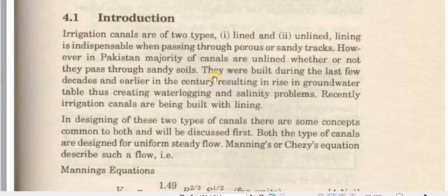And we will use the equations of open channel here. The sequence is that from the barrage we offtake the main canal, and the main canal diverts water to the branch canal, which diverts to the major distributary, and the major distributary diverts to multiple minor distributaries, and minor distributaries divert water to the water course from the outlet. We studied outlets in our previous lectures, chapter 8.